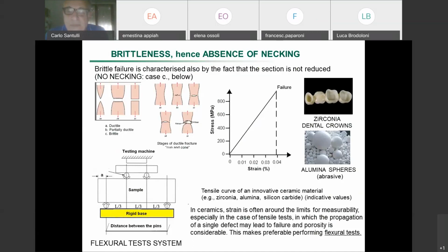When a crack propagates into ceramics, it may go between some different pores, and in the end it creates an effect of aggregation of the different pores and crack propagation. Crack propagation is enhanced by porosity, which might be a problem if you want a structural ceramic.